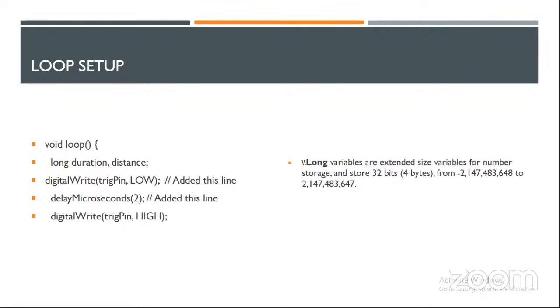As your question is how many LEDs in one Arduino module can be controlled? See, we don't have a limitation. But again, coming back to the same thing, if you are choosing Arduino UNO, you can give 13 outputs, so probably you can connect only 13 LEDs. So the input and output pins matter, and based on the pins, we can meet the requirements. Any doubt, guys?